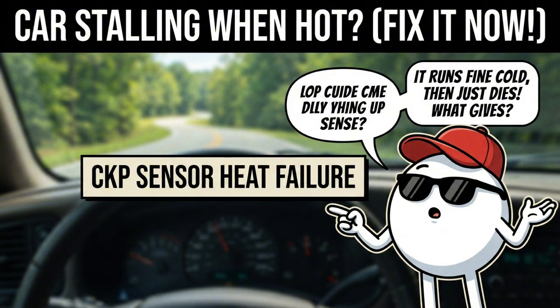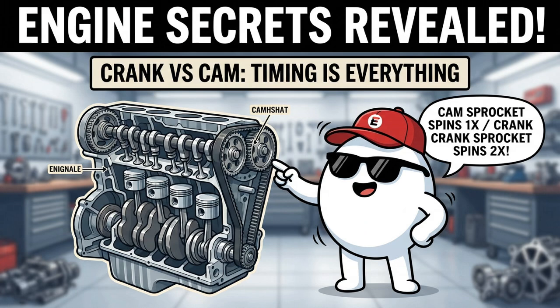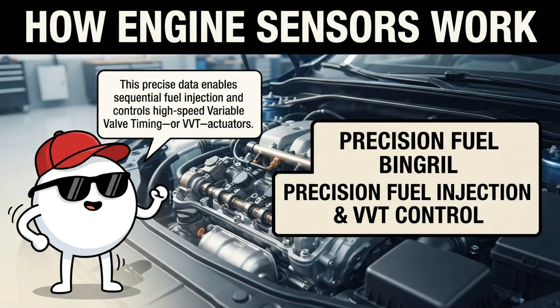reaches operating temperature. Working in direct synchronization with the crankshaft sensor is the camshaft position sensor, or CMP. While the crankshaft spins twice per cycle, the camshaft spins only once. The CMP tracks the rotation of the intake and exhaust valves to tell the computer which specific cylinder is on its intake stroke versus its exhaust stroke. This precise data enables sequential fuel injection and controls high-speed variable valve timing, or VVT actuators.